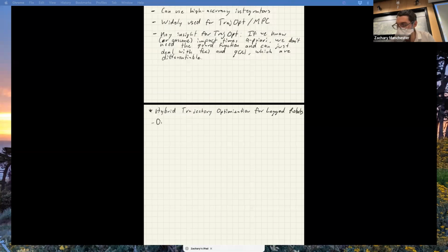Okay, so here we go. One-legged hopper. Here's the cartoon. Got a ground. You've got a body, we'll call it M sub B. We've got a foot, M sub F. We've got a prismatic joint connecting them together. And we can exert a force here, F, through that prismatic joint. And then we're also going to assume that you can exert a torque to swing the leg around. So you've got the F and you've got a tau up here. And that's basically what the Raibert hopper looks like, except the Raibert hopper's in 3D. So this is kind of a simplified version.